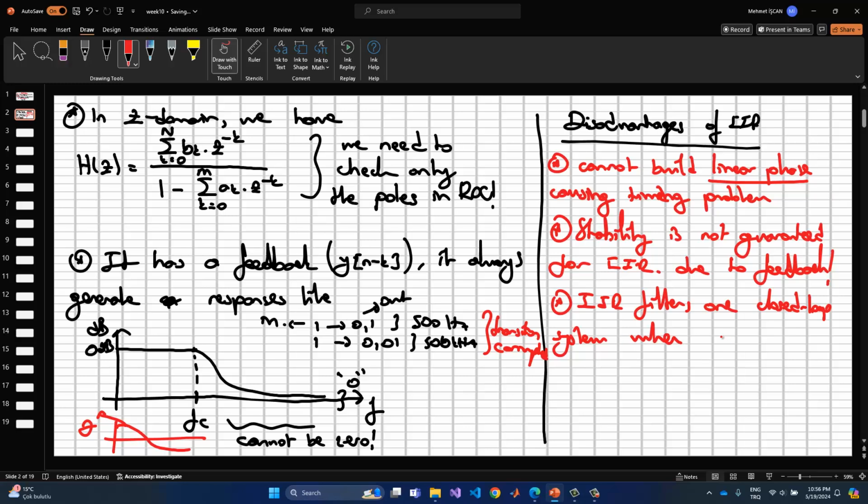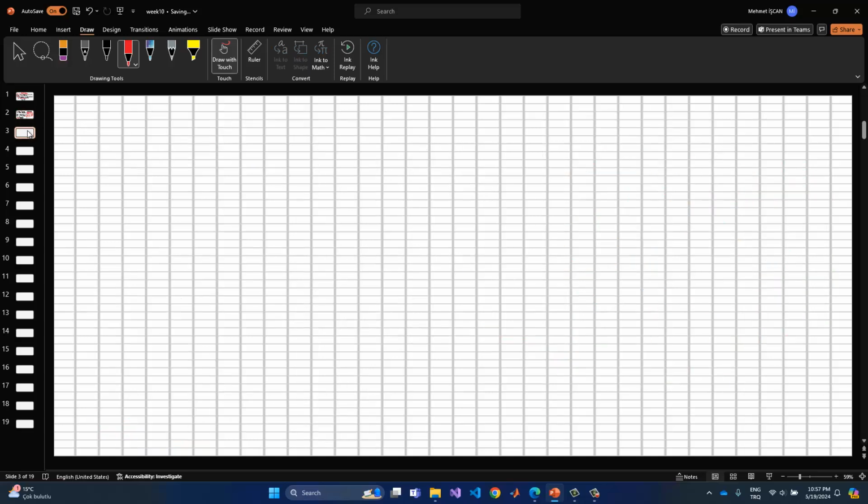When the finite impulse response filter is an open loop one, the FIR filter does not require any feedback components. The IIR filter, however, should always store the past values of the input signals and the filtered signal itself.